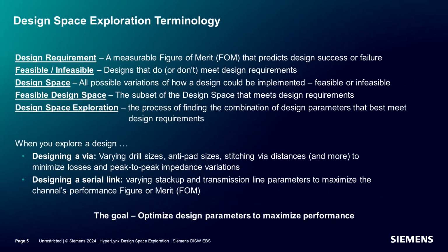First things first, let's understand what we mean when we say we'll be optimizing using design space exploration. In the world of PCB design, a design space is defined as all possible options of what a design could be, feasible or infeasible, with any and every parameter option accounted for. This means all possible experiments one may run, looking at varying trace width or length or via spacing, pad sizes, and potentially millions of combinations.